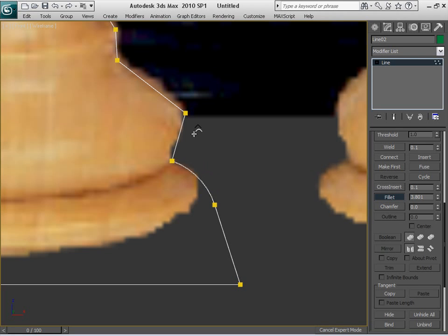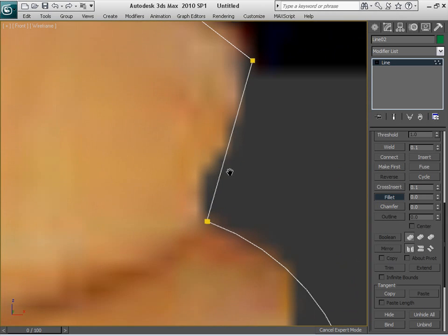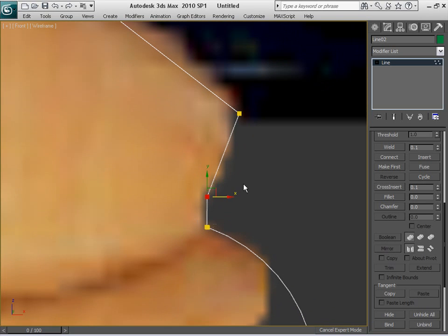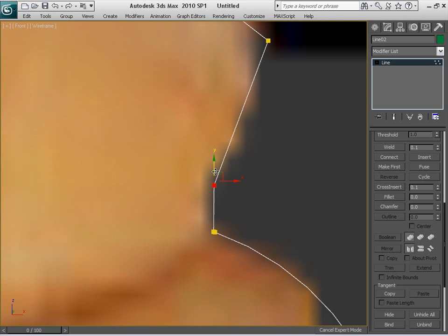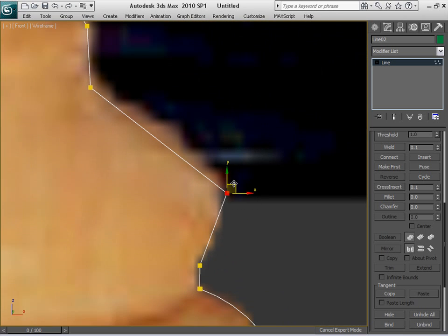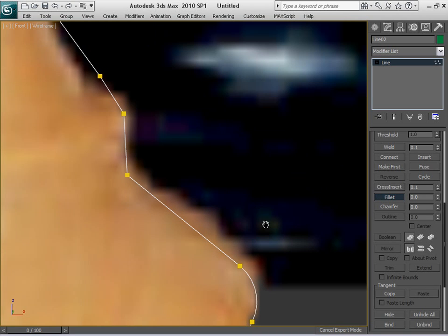and I'm going to make the roundness here. In this case, I want to add this particular straight line before the roundness here. So what I'm going to do is right click and select the option refine, and that way I can insert a vertex inside our spline, and that way we're going to have a straight line first, as you can see, and then here we're going to use the fillet command to create the roundness that we were talking about.